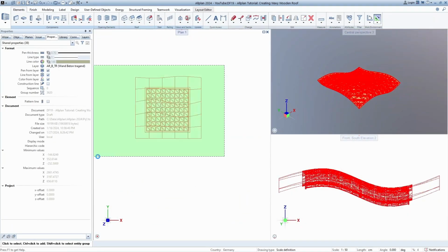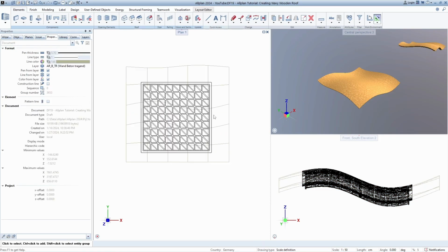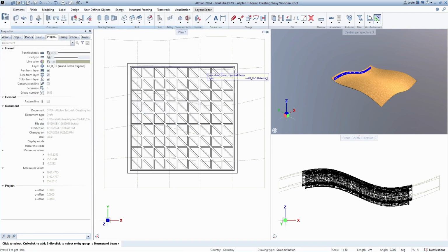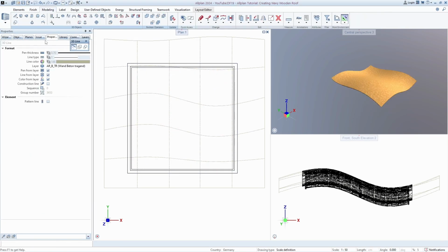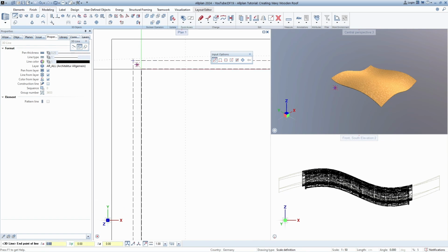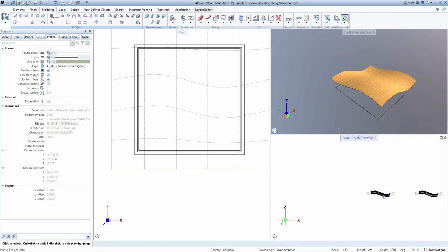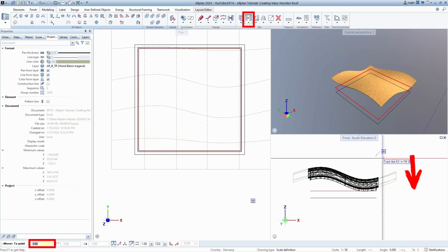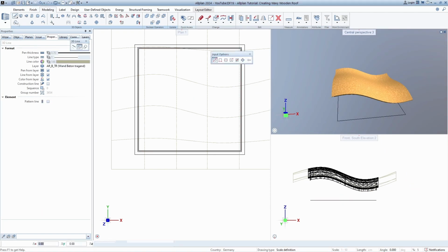First, we copy the entire model for some known distance, for example 50 meters. Then, using the same filters, we will delete all inner beams and draw one 3D square, taking into account that it's located inside the edges of the beams. In the side view, we will select the square and move it along the Z-axis by 250 cm down. Draw a new vertical 3D line that goes beyond the highest point of our roof.